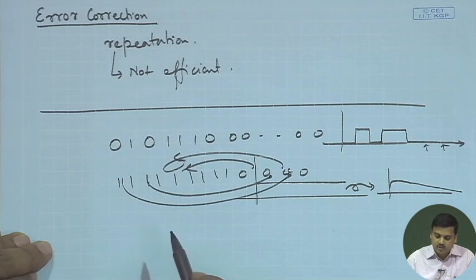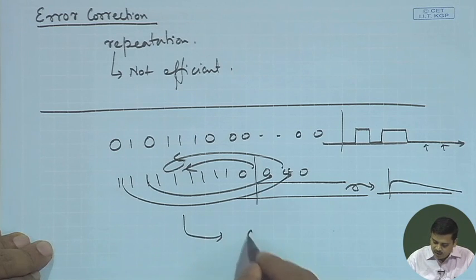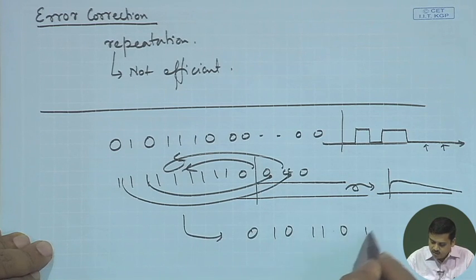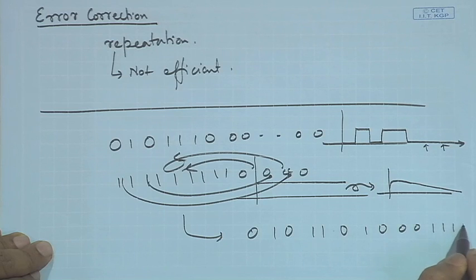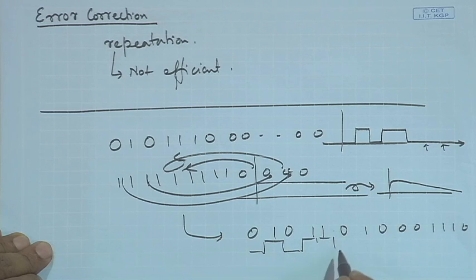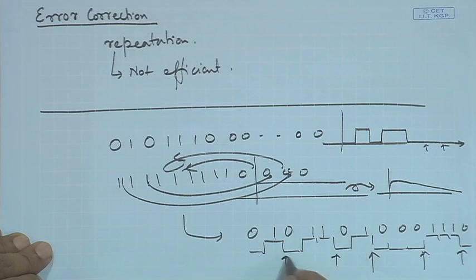So, that is the job of the scrambler, so that finally you end up with a sequence where there are random ones and zeros, so that you keep getting your clock at least at a certain rate. So, at least there is a change, there is a change, there is a change. When you do clock recovery, you will find that these edges become very, very important for recovery of clock.